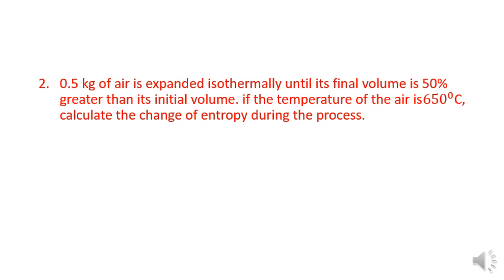So here, the given condition is that it is expanded isothermally. Isothermally means constant temperature. So we have to find the change in entropy during the constant temperature process, and the formula is delta S is equal to mR ln V2 by V1.